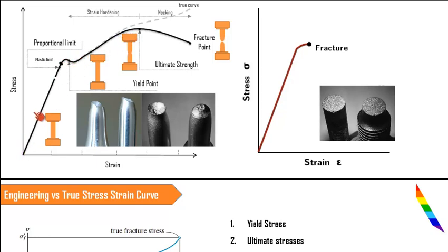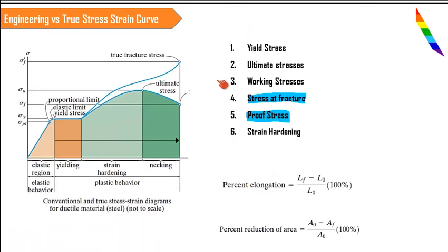It will be something like an arc, so this much detail may not be available. The proof stress is based on an assumption that generally the yield point is obtained in a material at 0.1 or 0.2 percent of strain. That is an important assumption that we make.